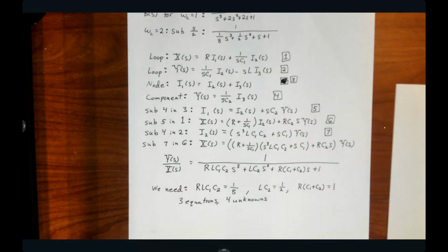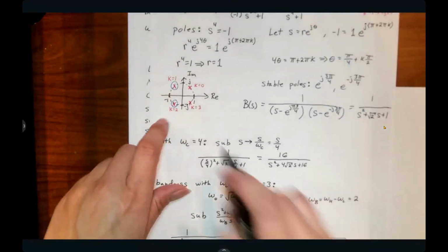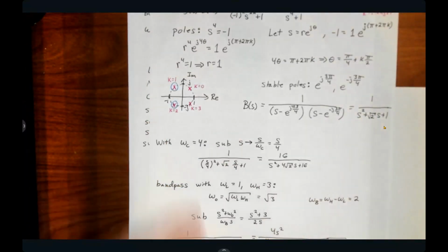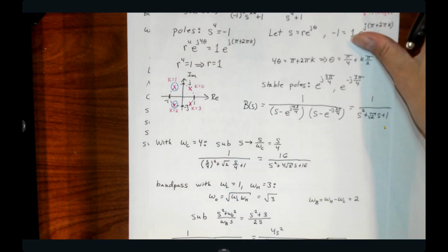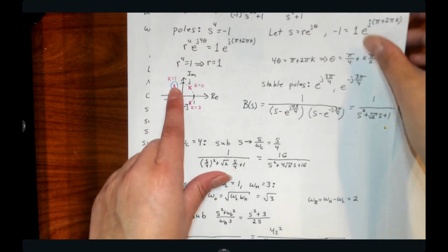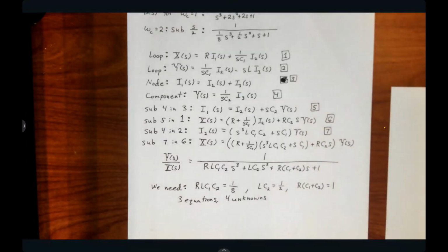So the main advantage there is being able to look at this idea of the poles, right? So we have that concept of stability of this transfer function. And by getting it into the Laplace domain, we're able to take a look at those poles and form a transfer function, which gives us the type of frequency response that we want.